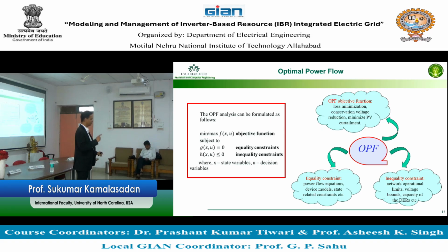Generally, you don't cut. Curtailment means behaving good photovoltaics, you cut. That is curtailing. Okay, what do you mean by that? So let's assume that the photovoltaics are allowed to supply maximum power from the solar farm. Maximum power, have you heard of maximum power tracking? So maximum power comes from the photovoltaic. Now let's say this maximum power comes from the photovoltaic and you are allowed to put it on the electric grid. What happens if this maximum power at some point of time increases the voltage to above 1.05?